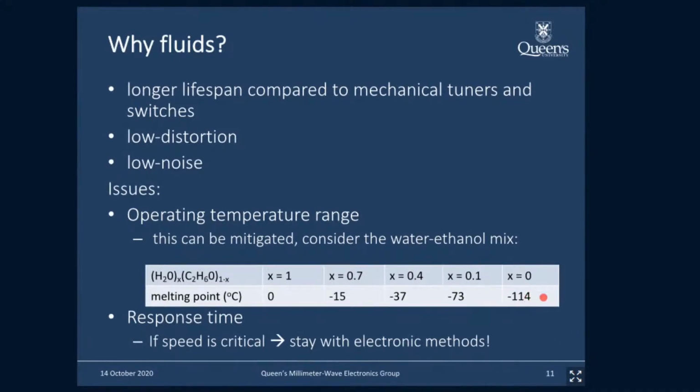What you also have to take into account, of course, is that your permittivity will change, depending on what that mix is. But then again, you can characterize that. The other thing with fluids, of course, is the response time. If you have fluids moving in a channel, clearly your response time is not going to be comparable. Your switching time, for example, of an on-off switch will not be comparable to electronics. So if speed is important, then you will want to stay with electronics. So in what situations do I not care so much about speed? Well, there are actually many.